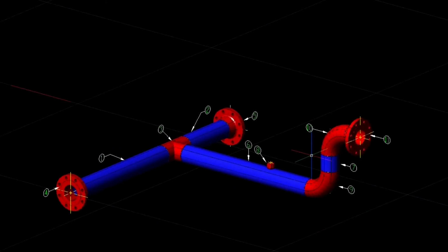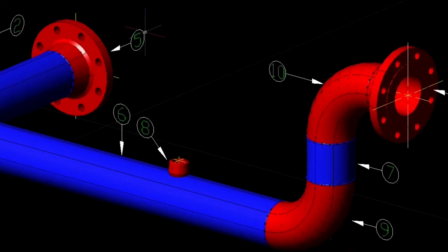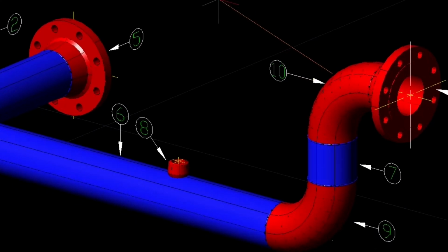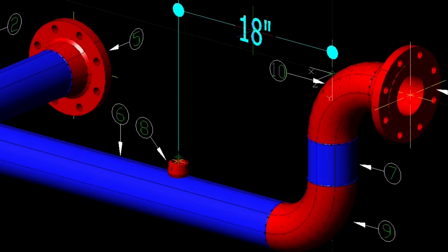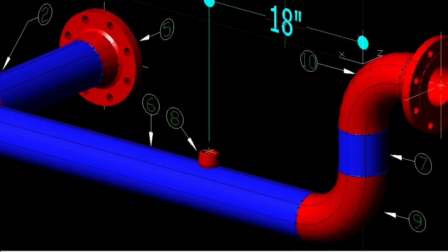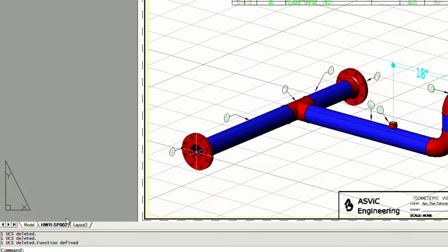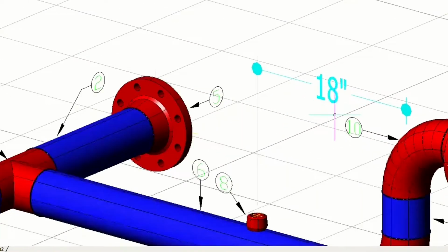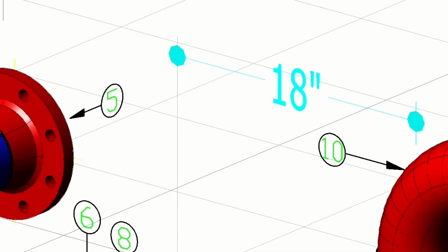Like most spool drawings, this one is displayed at a best fit zoom factor, which means there is no formula to figure out the model space to paper space ratio. Therefore, in order to figure out the proper DIMSCALE, I place the dimension in model space. Then I switch to paper space. Next I adjusted the viewpoint to get the view and magnification factor I wanted to use and measure the text height in paper space.